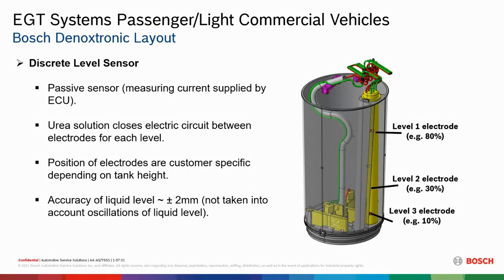But the problem with these is that they were probes sitting in there, and they were in a corrosive atmosphere. So these probes got corroded. Corrosion actually worked its way up into the wiring of the system, and once it got into the wiring, it corroded the wiring and caused resistance issues, and then caused input issues to the ECU.